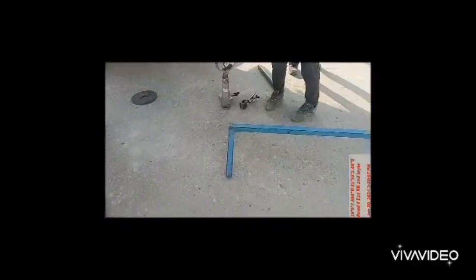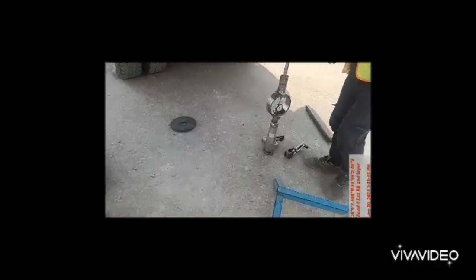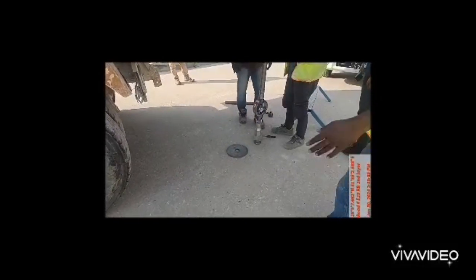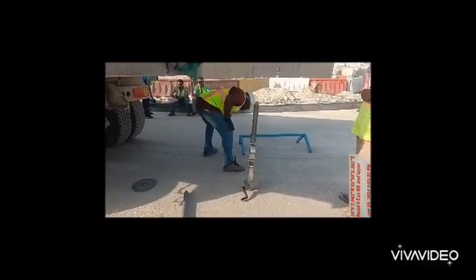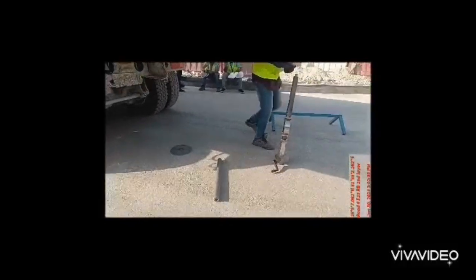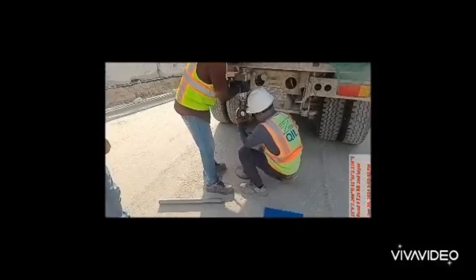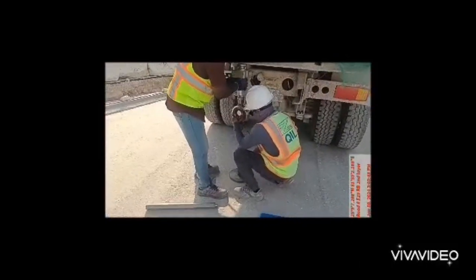The procedure for the CBR is the same as for the subgrade final layer, the only difference being the CBR value. The minimum CBR required for the subgrade is 95%, and for the road base the minimum CBR required is 80%.